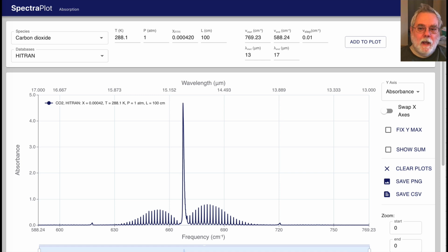If you use a wide range or too small a step size, the tool may calculate for a couple minutes and then give you one of several errors. You can narrow your range and/or increase the step amount and try again. The vertical axis defaults to absorbance, which we will keep now. Later we will select transmission.